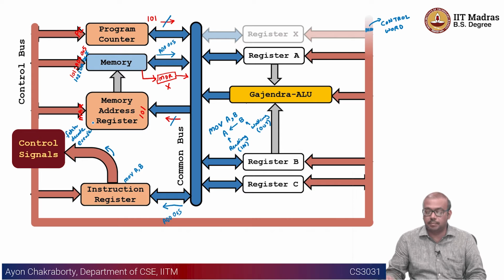If it is not a data movement operation like move, if you want to do an add, subtract, multiply, divide, whatever, if the ALU supports it, this is typically a combinational circuit operation, and that is going to be completed in one clock cycle. Okay. There could be instructions that require multiple clock cycles for the execution, but for now I am going to keep the discussion trivial, specific to trivial kinds of computations like add, subtract. Okay, so just to be clear, our ALU is going to support add and subtract.